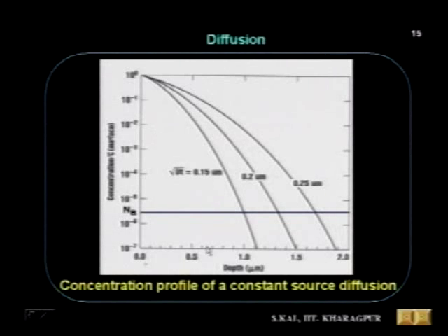At the surface, dopant source is constant. Now with time also, with x equal to infinity, it will be 0. So this is the x axis, that is depth. x equal to 0 is the surface. If you increase x, that means you are going deeper and deeper from the surface, at a larger distance from the surface of the silicon, at a larger depth. Now, this is the complementary error function profile, which agrees with the pre-deposition diffusion.